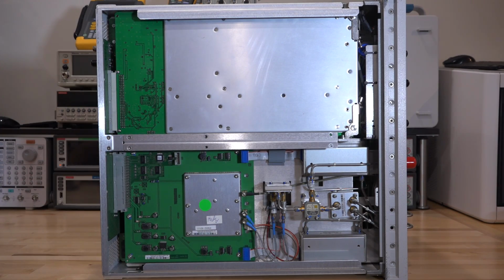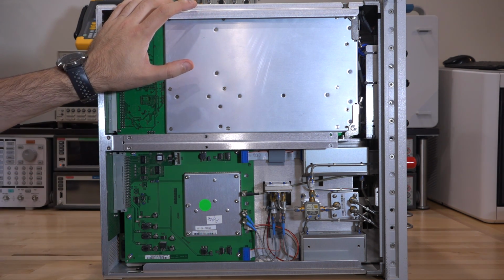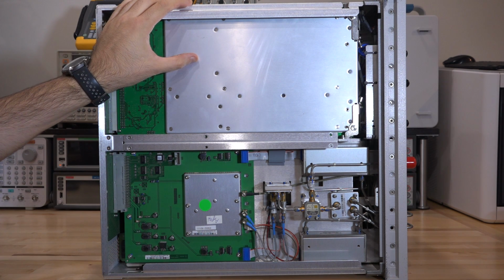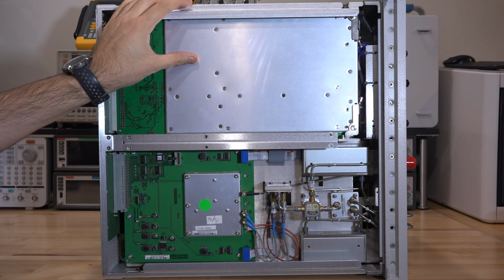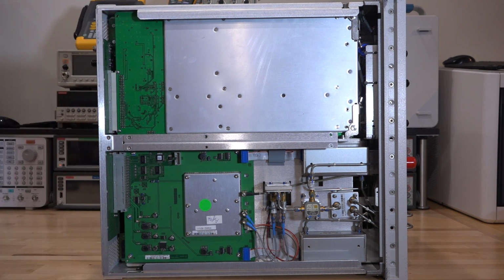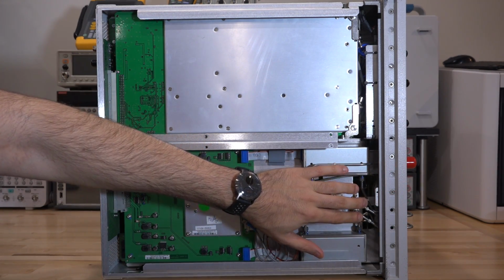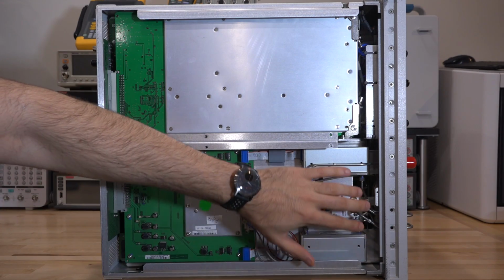And here's the bottom of the unit where all the RF stuff is connected. Now, of course, these boards are all going to have all the RF magic that includes down conversion, digital RF, digital PLL, and all the other things that I spoke about. But the front end microwave components are present here. So the input comes over here. You can see that we go into a power splitter. This power splitter has 2 outputs, one on this side, which then splits into 2 again. And these 2 go outside of the unit and back in, so that if you have the frequency extender, you can connect it to it as I showed you.